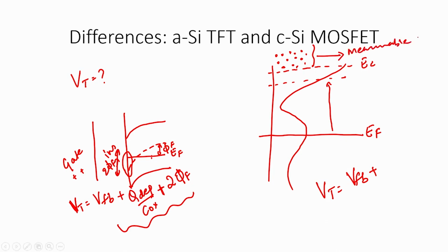So, that is the definition of threshold voltage, which is a very vague definition, because it depends upon your density of states profile. If the density of state distribution is very large, you need to trap a lot more carriers before the Fermi level can climb to that point, and therefore your threshold voltage is going to be much larger. So, let us say that this is the location of the Fermi level when there is significant carrier population in the extended states.